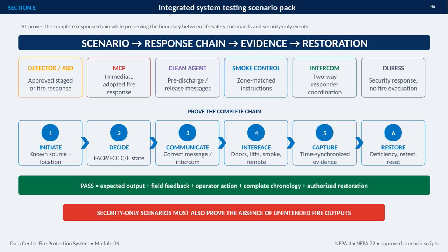This section focuses on integrated system testing, or IST, for the data center fire protection system. The goal is not to test isolated devices, but to prove the complete response chain, from an approved scenario through system decisions, communications, interfaces, evidence, and restoration.